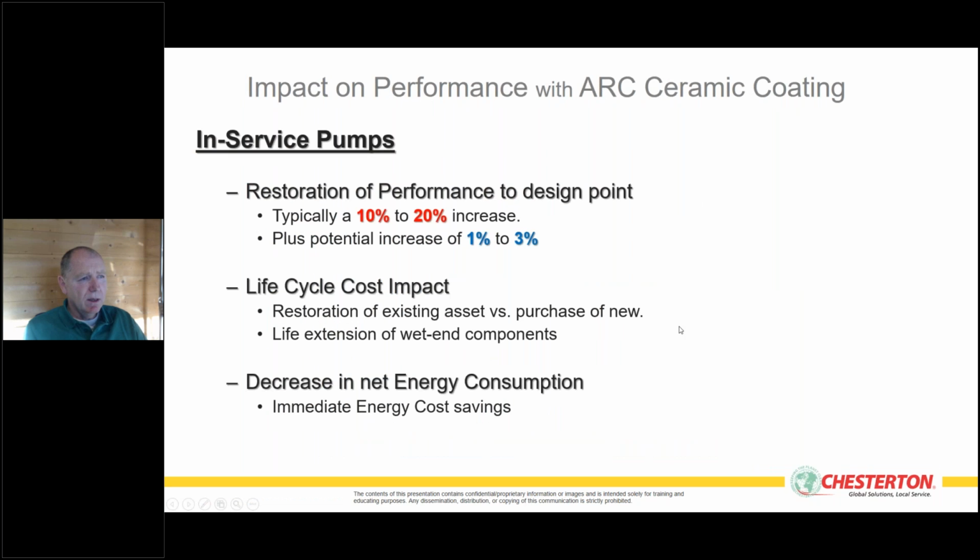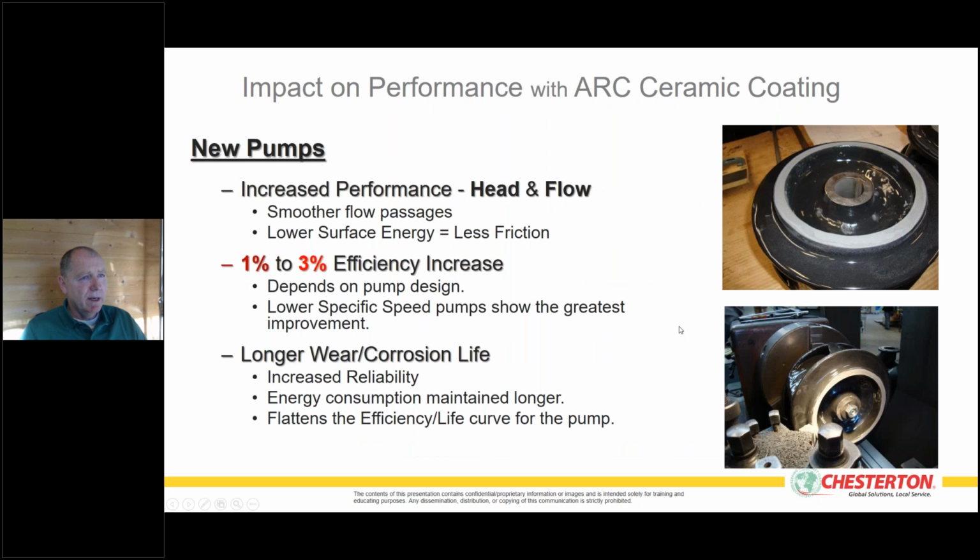So, as I said, we can look to achieve this by addressing new pumps, to increase the performance of new pumps by improving the head and the flow, making smoother flow passages with low surface energy materials, reducing the friction. This has been shown many, many times to allow an efficiency increase of up to about 3%.